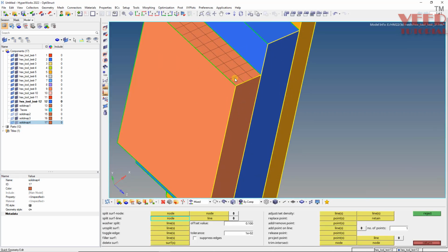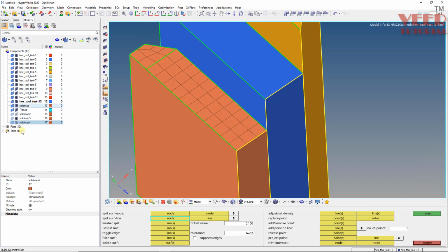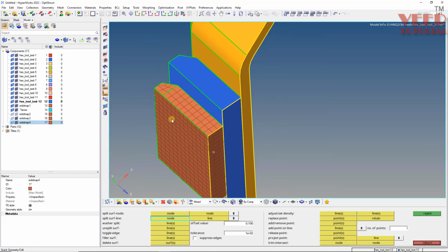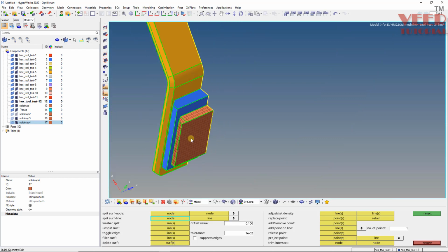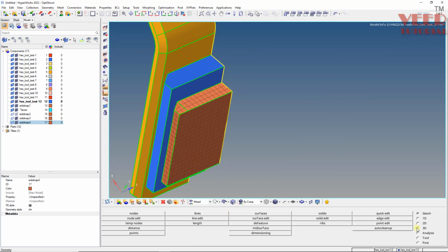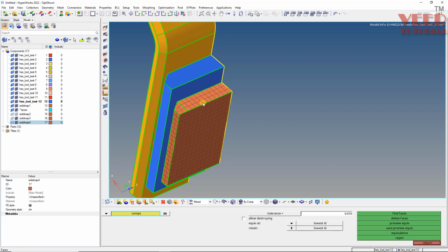So we have done the meshing of this part. So I will turn on mesh of this part. Okay, now I need projection. For the projection we need its faces. So press X for the faces, pick this and find.